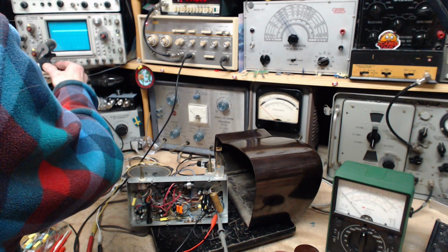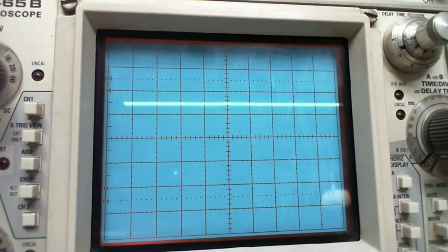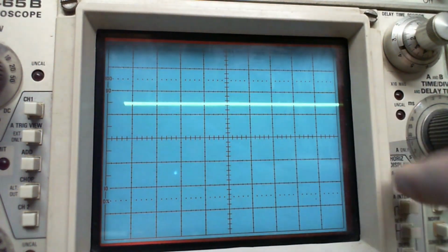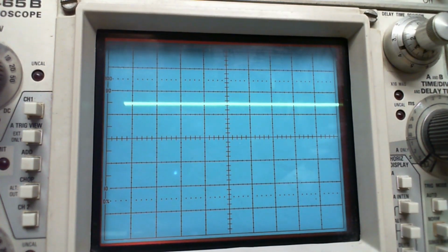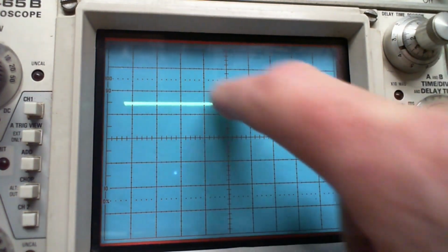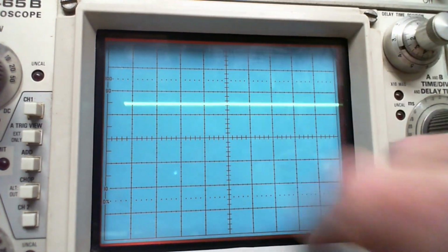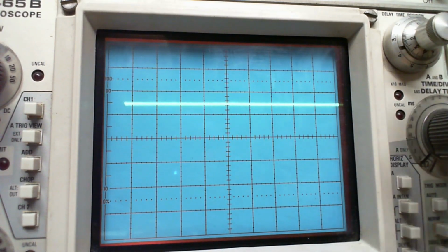There's nothing on here now. So I have a camera up there. You can get a close look at the oscilloscope display here. Now the oscilloscope is not sweeping on its own. I have it set to sweep based on a sweep signal coming from the sweep generator. So that's why it's always low frequency here, high frequency there. Somewhere in the middle is the 455. And somewhere in there hopefully we'll see a resonance, but I don't see a thing yet.